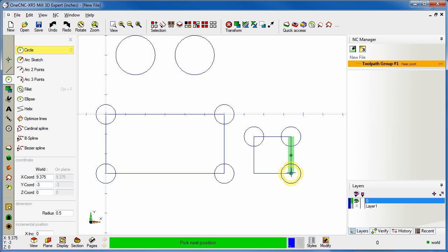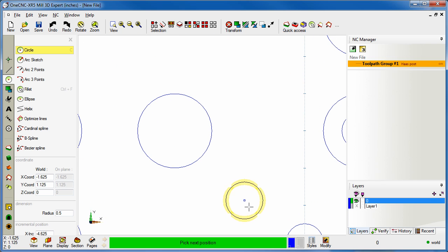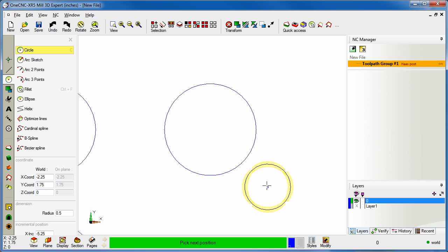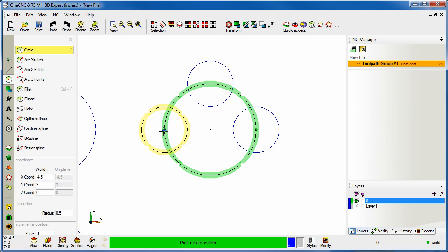We can do the same thing with arc centers. Let's just move our cursor up here, grab the arc center and left click and left click. How about midpoints? Same thing. We'll just grab the midpoint marker, left click and left click. In fact, if you'd like, you can even create geometry on the circumference of an existing circle. Let's do that right here. I'll grab right here at A0, how about up here at A90, and over here at A180. Very, very quick. Now you can also dynamically snap the circumference just by moving your cursor and snapping where you'd like.